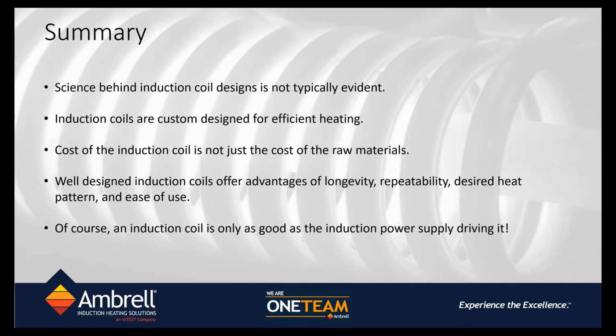So induction heating coils are able to heat any metal that is in the vicinity of the copper coil. It can be a roller, it can be a cylinder. So in a roller type process, we would imagine an elongated long coil that is able to heat the roller, and the roller is turning in front of the coil.